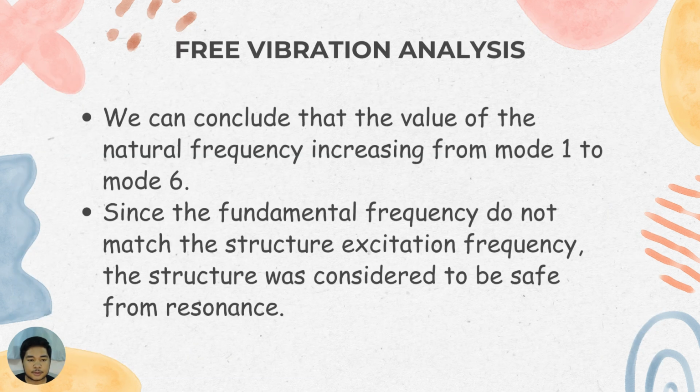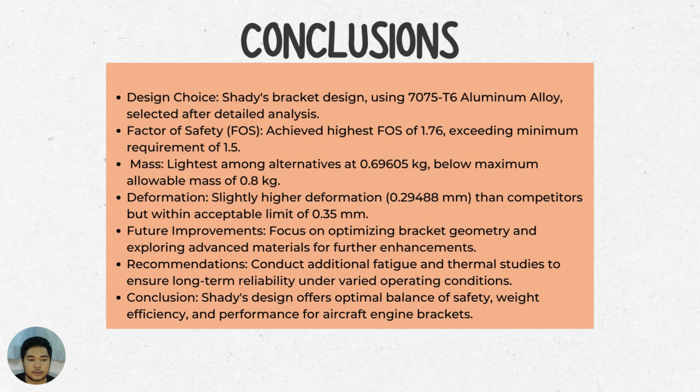From the result of free vibration analysis, we can conclude that the value of the natural frequency increases from mode 1 to mode 6, and since the fundamental frequency does not match the structure excitation frequency, the structure is considered to be safe from resonance.